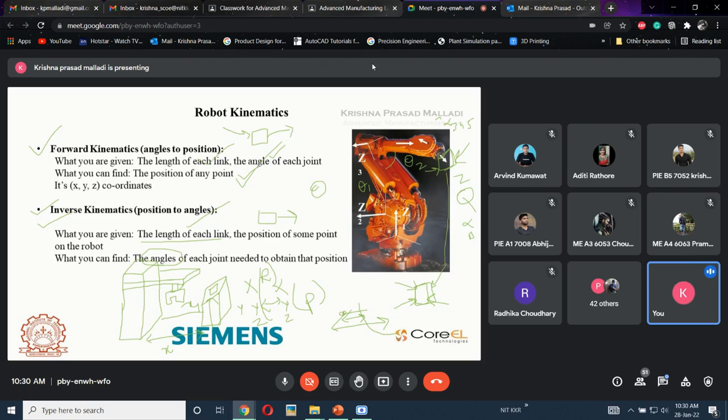Okay, see, this is a robotic part, that's why I'm just explaining in outer ways. But for forward kinematics, there will be some matrices with which you are going to calculate. Same with the inverse also, there will be some x, y, z and alpha, beta, gamma. There will be a 3 by 3 matrix. By using this 3 by 3 matrix, you can calculate theoretically if you want, and you can correlate the actual value with the virtual value.